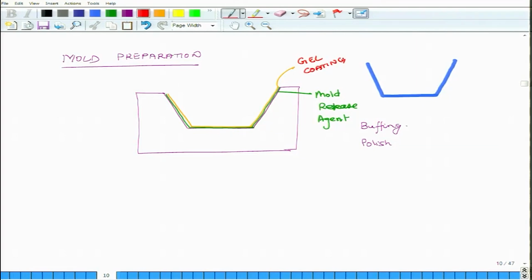And this makes sure that the overall surface has no roughness and it is pretty smooth. So, this is how you broadly do the preparation of the mold, and then you start putting fibers. Now, in context of fibers, I wanted to say two things. You can put fibers in two ways. First way is, it depends on the requirement. So, there could be a reason why you are interested in putting some randomly oriented fibers.